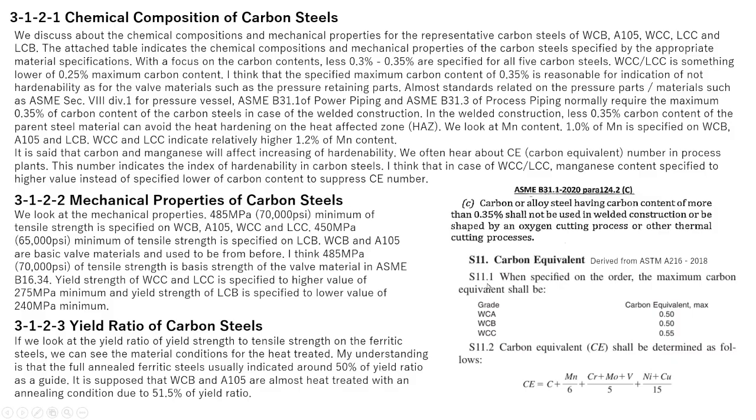If supplementary requirement 11 is specified for the casting material, WCB casting specifies a carbon equivalent number of 0.5% maximum to be controlled. WCC casting carbon equivalent is 0.55% maximum.